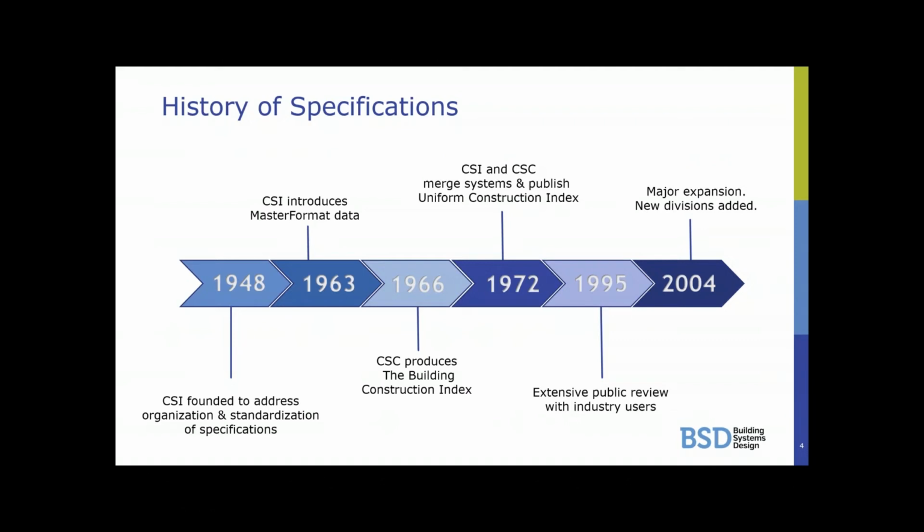The standard for organizing specifications and other written information, known pretty much as the Dewey Decimal System for building construction. It's used throughout the construction industry to format specifications. It is now 50 divisions. Each division is divided into a number of sections. For instance, Division 9 is finishes, and one part of that is 093000, which is tiling, or 099000, which covers painting.